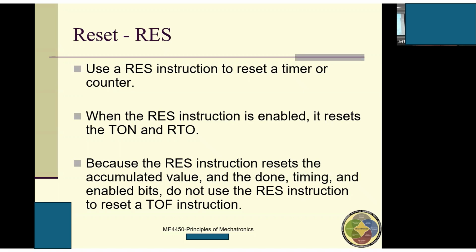If you reset it, you will send out a true to false transition, and this true to false transition will trigger the timer, trigger the TOF. That's the reason RES should not be used for the TOF.